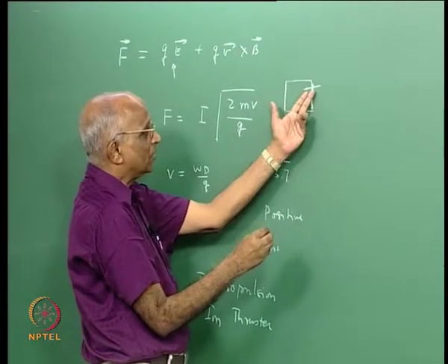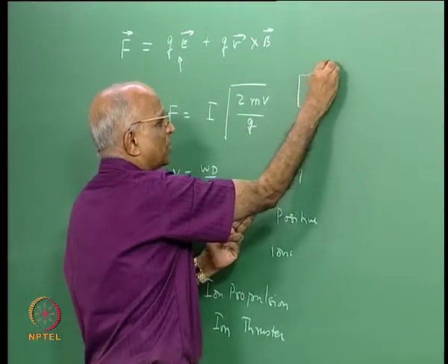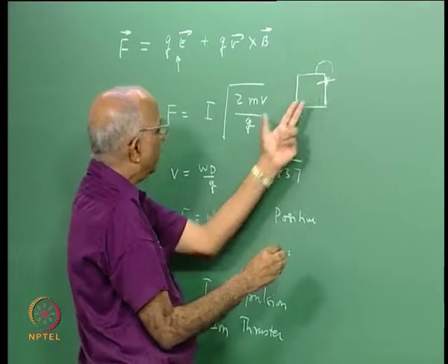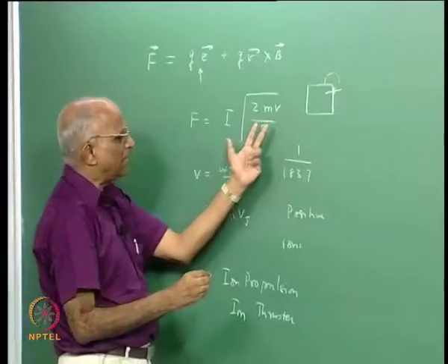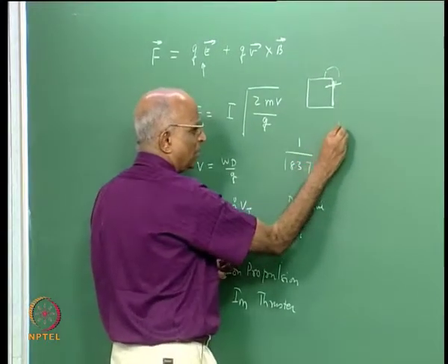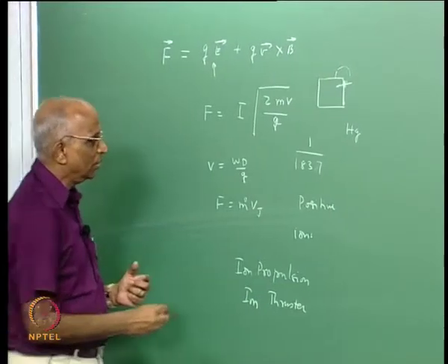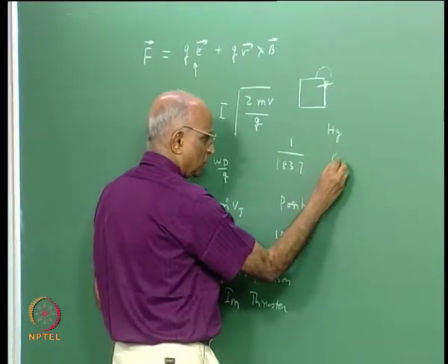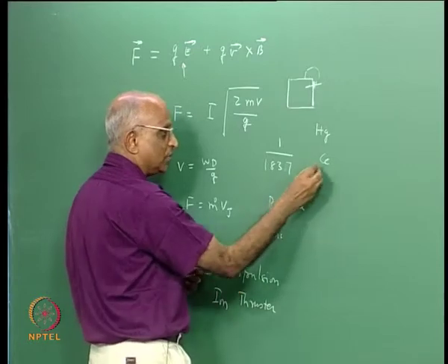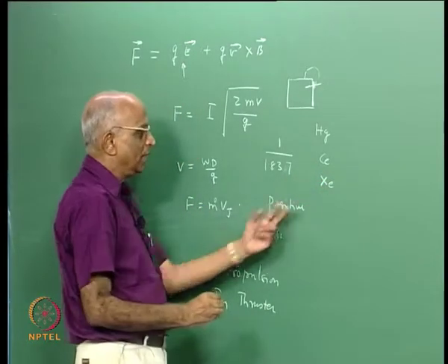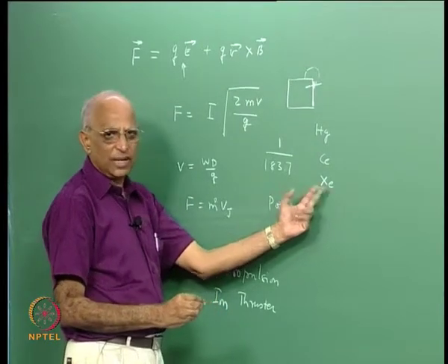If mercury is let off from the spacecraft it will go and form a monolayer on it and make it opaque, and therefore mercury is generally not used. It was used in the earlier spacecraft and is no longer used. Maybe cesium was also used but no longer, because it is a reactive metal, and what is universally used today is xenon, which is a noble gas.